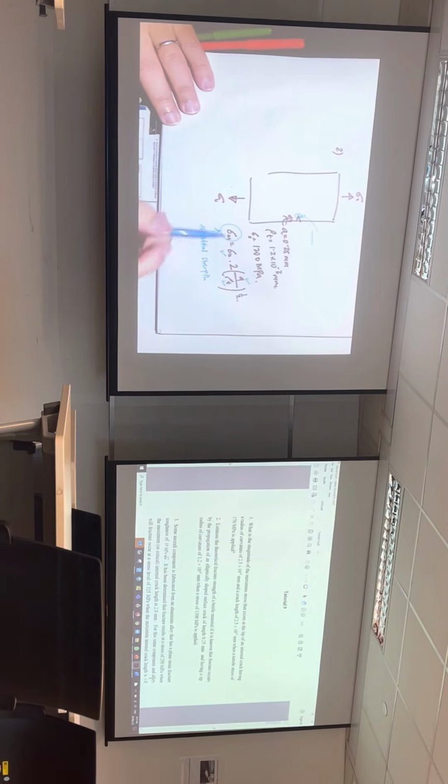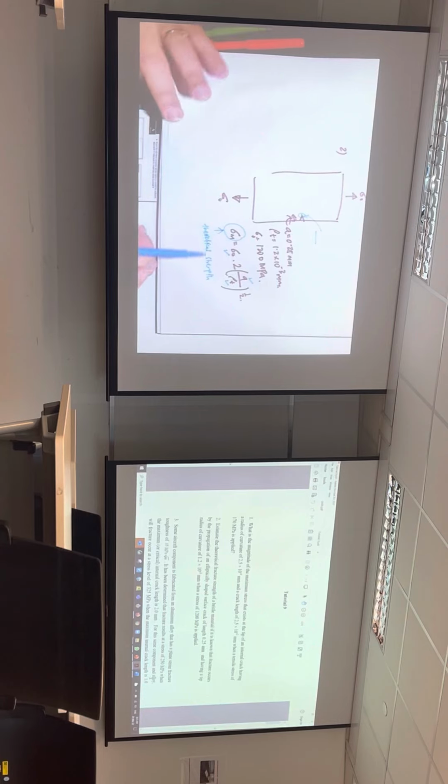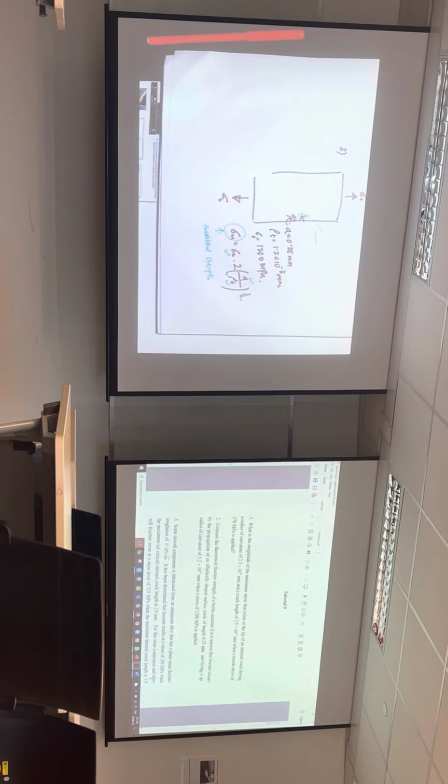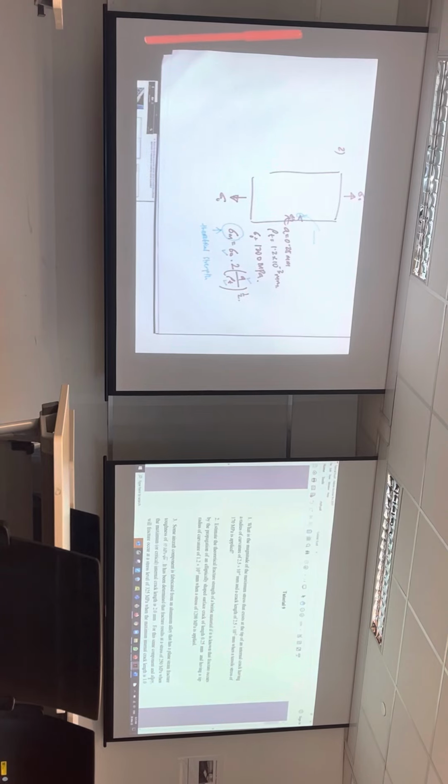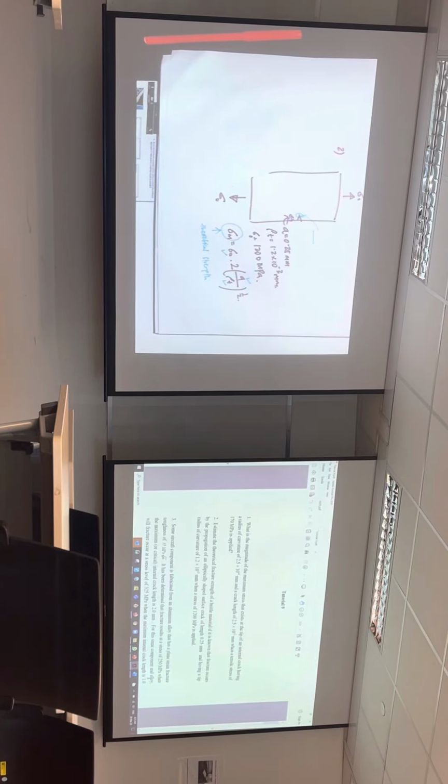Because at this particular juncture, the thing fails. Just imagine I pull with a stress of 100 megapascal, there will be a sigma m. It doesn't pass the material limit. I go to 1,100, nothing happened. 1,150, nothing happened. When I go to 1,200, oh, fail. So at 1,200, the corresponding sigma m value exceeds the material properties at the tip. And once it exceeds, the whole thing will just go. This is what the question is trying to say.